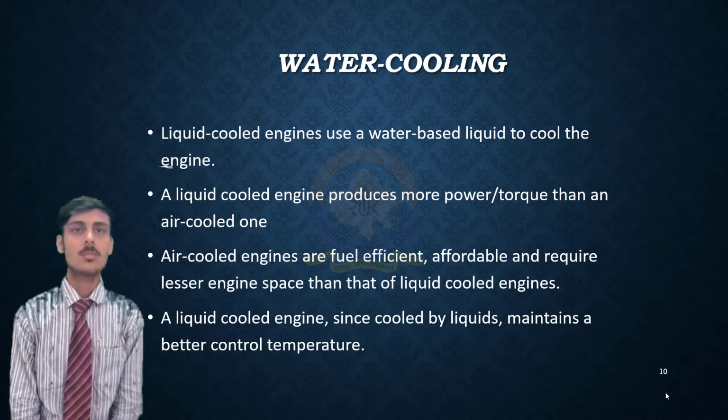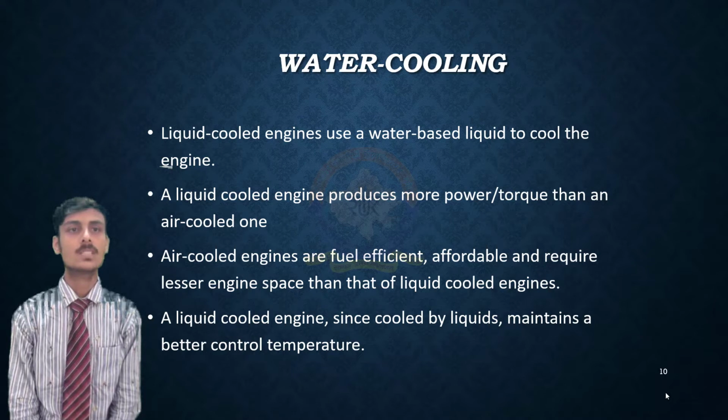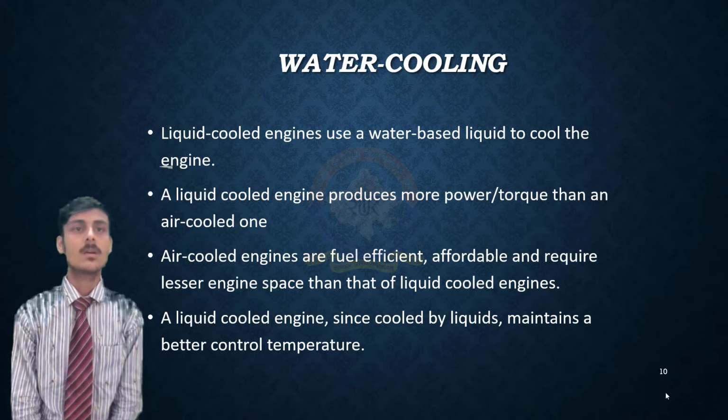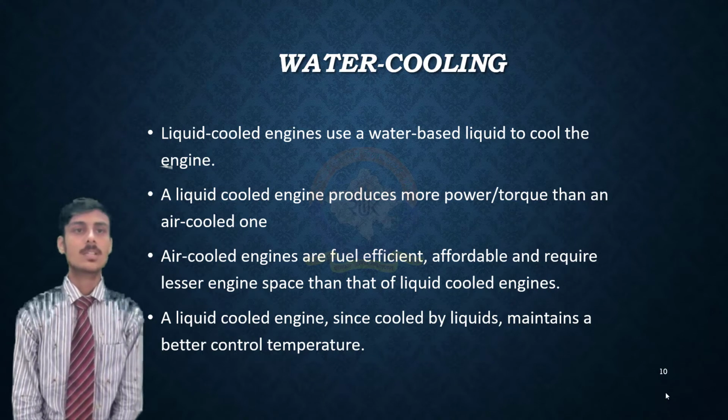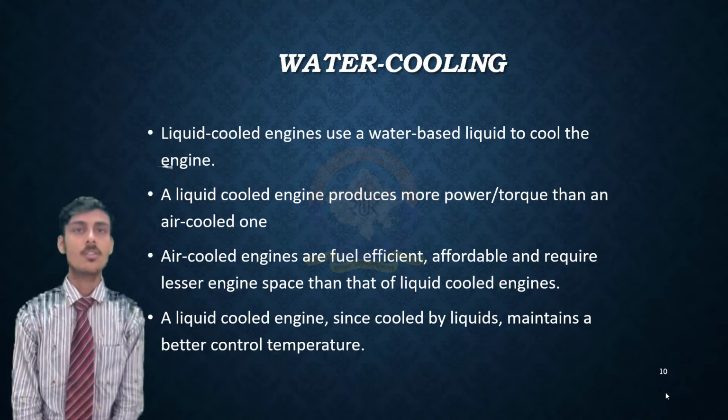The water pump has the job of keeping the fluid moving through this system of hoses and hidden passages placed between the engine and the radiator, to make sure that the coolant stays above a certain temperature. If the coolant temperature falls below this temperature, the thermostat blocks the coolant flow to the radiator, forcing the fluid instead through a bypass directly back to the engine.